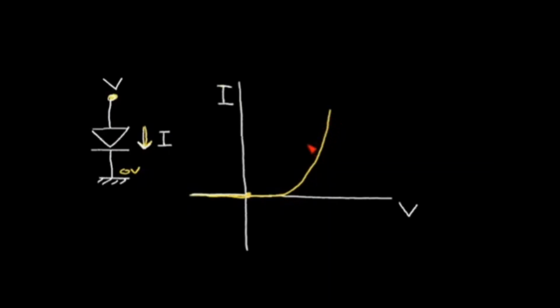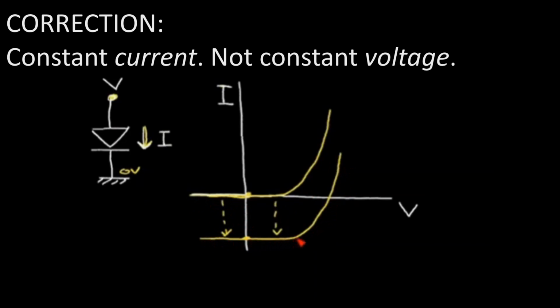Now, what happens if we shine light on the silicon diode? So let's look at what happens if we add some light. Now, this produces a different curve. The light causes this curve to be shifted down like this. And so at this point, we have current flow. We have more or less a constant voltage, and the current drops off to 0 current at this point.